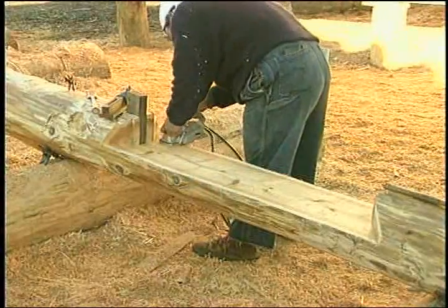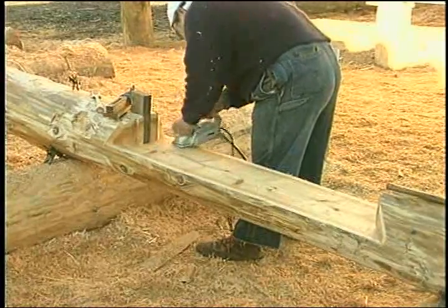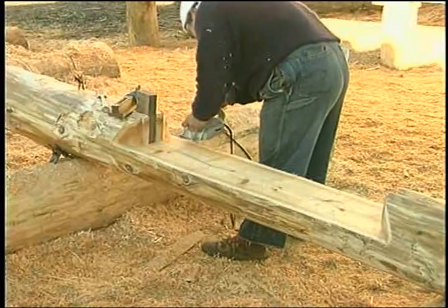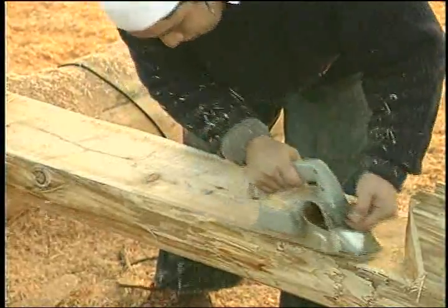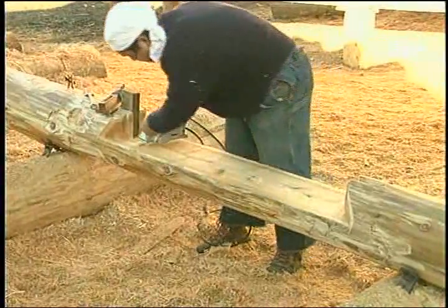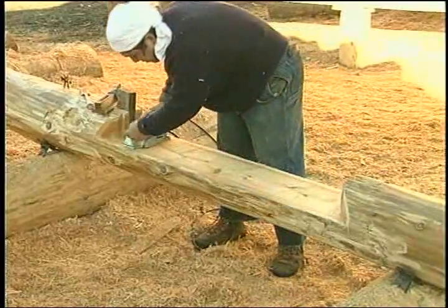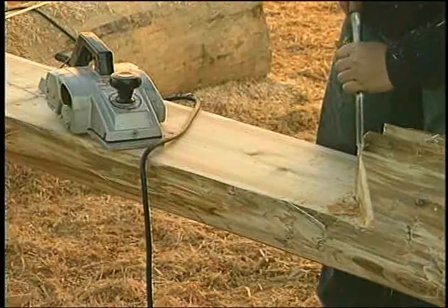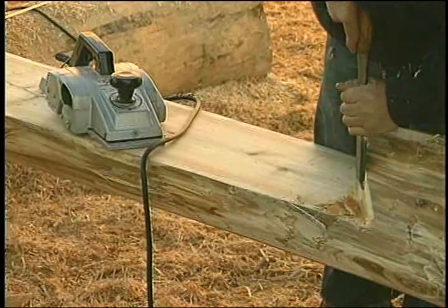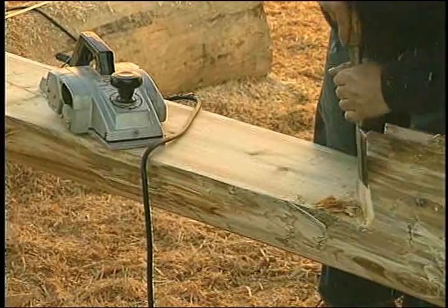Use a small power plane or hand plane to finish the top of the opening. I would rather not use a sander here because good alignment of the work will allow the trim to fit better. Finish around the ends of the cut with a chisel or slick. Then cut out the notches and groove in the regular way. At that point, the header log is ready to be replaced on the wall.